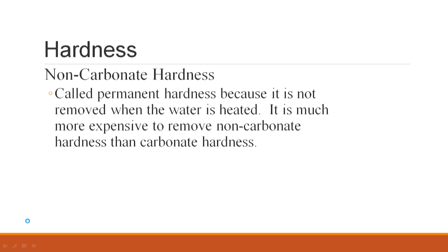So, non-carbonate hardness is called permanent hardness because it is not removed when the water is heated. Well, that is a very roundabout way of describing things, but we will look at why it turns out to be permanent hardness, and obviously it is much more expensive to remove when compared to carbonate hardness, right.